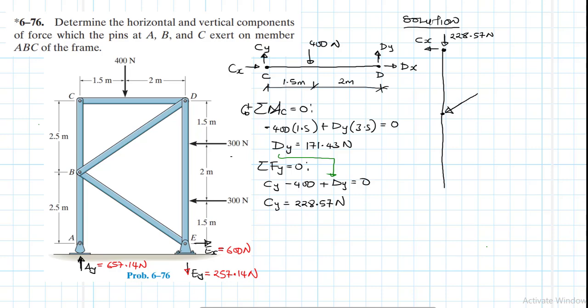If it is not, it's going to give me a correct value as I do the calculation. And in BE, I'm assuming it is in tension, and we have the slopes that I want to just indicate here. The slopes for BD, I have a run of 3.5 and a rise of 2.5.